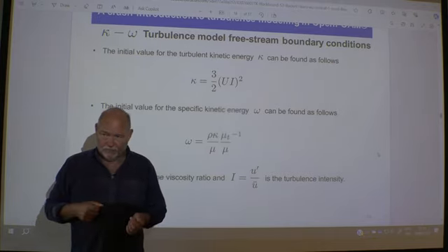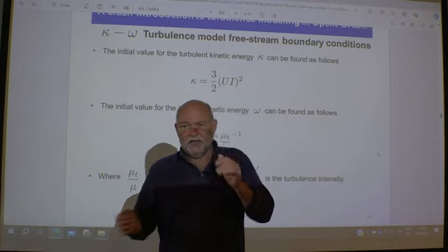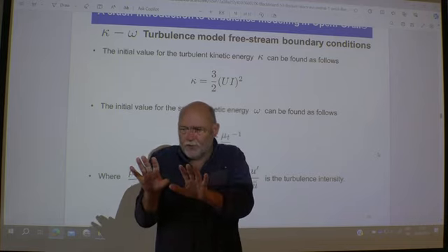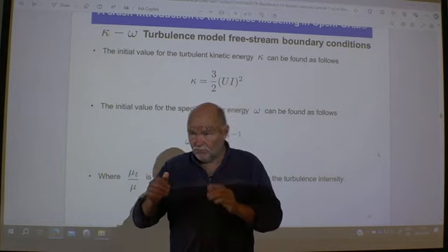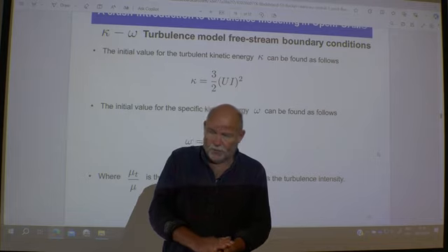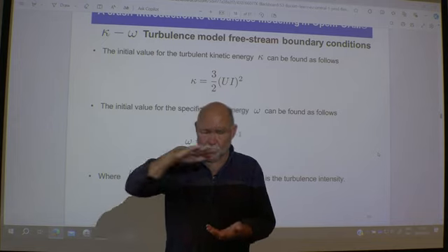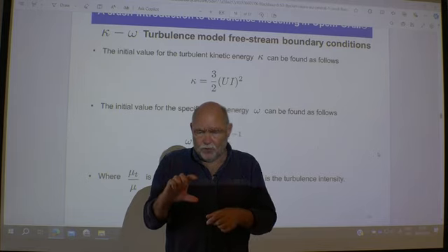That's not good. As a rule of thumb, your mesh should be smooth and nice. So you shouldn't have too much change in area from one cell to the neighbor cell. In the old days, we said 15% change. That means it has to be sort of smoothly stretched. Nowadays, they can handle more. So you can go from size 1 to size 2.